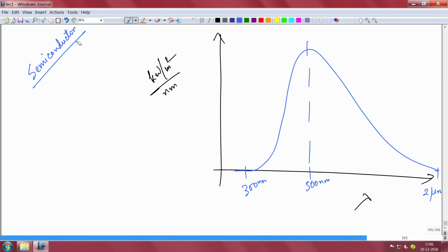Of course silicon works as a solar cell, and the good thing is that silicon actually works as a very good solar cell. You will see that silicon's efficiency is not bad actually, it's very high. I will not tell the number right now, but silicon will be predominantly used as a solar cell. I am talking about crystalline silicon, where you have a band gap, and you grow it by the Czochralski method or so. Crystalline silicon solar cells will have slightly better efficiency, but it's a little bit costly. I mean, it's cheap, but it's a little costly compared to amorphous silicon that I call a-silicon. Amorphous silicon is non-crystalline silicon. It's cheaper and you can use it at wide scale, although your efficiency will be a little low.